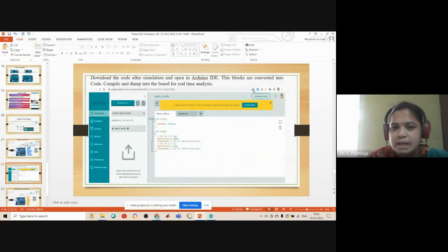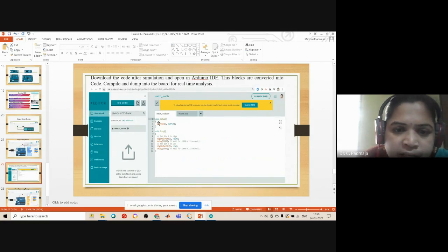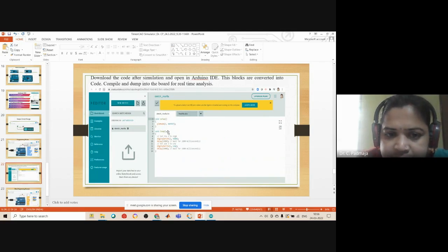This is an editor window for the arduino.cc. So whatever file we opened, that is pin number 2. This is the particular C++ code, which consists of two functions: the setup function and the loop function. The setup function consists of the predefined variables, but the loop acts as the main loop. Whatever controlling we want to do, everything we have to clearly mention in the loop function.